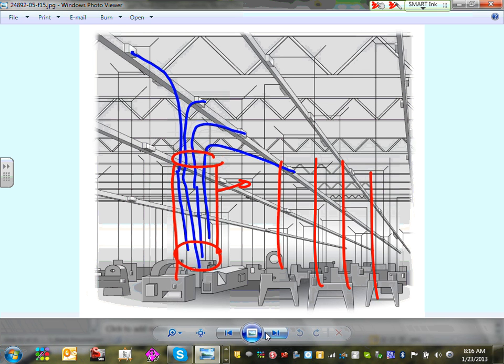And then we talked about the trolley busway, and we have 4 of them located at predetermined locations right at the top of the assembly line. If you ever get into a manufacturing floor, here are your 3 very good options for bringing power to your manufacturing assembly line. Any comments, any questions?